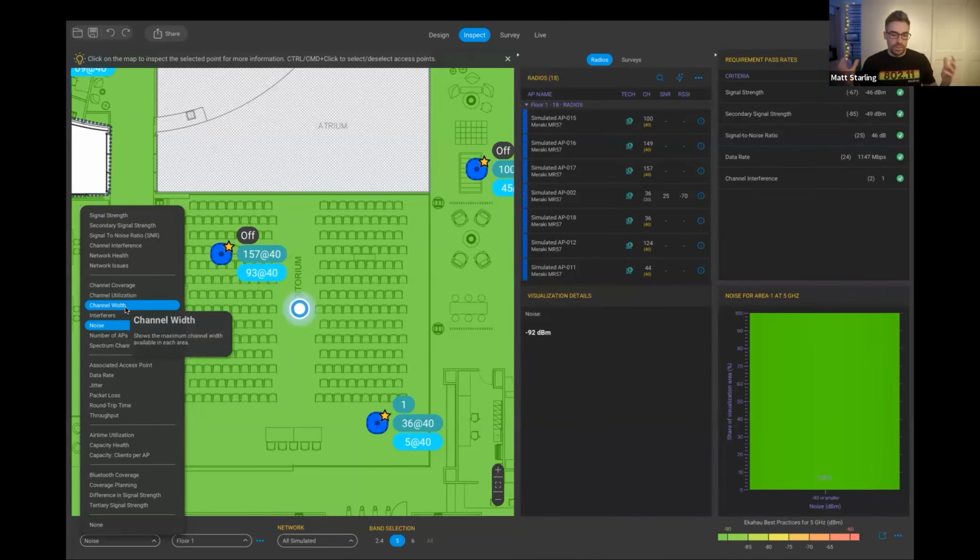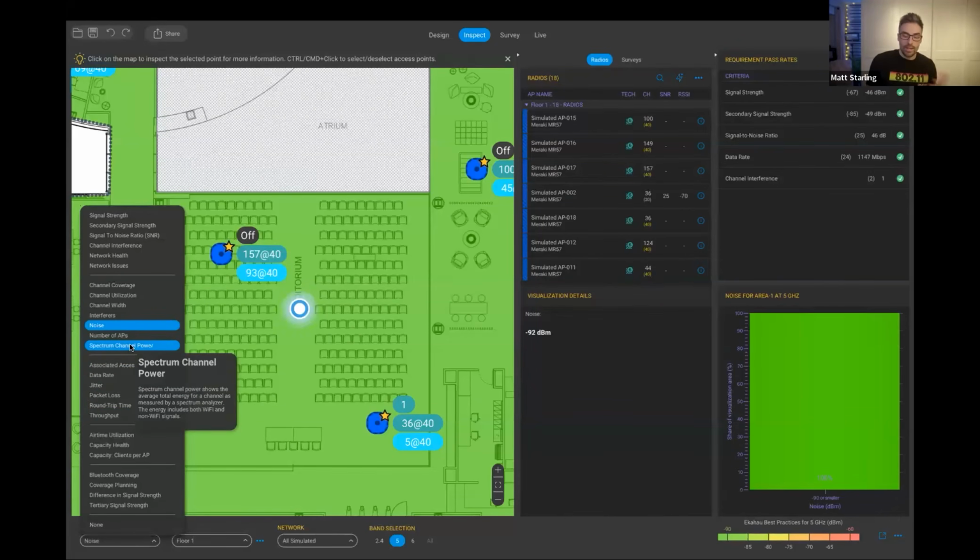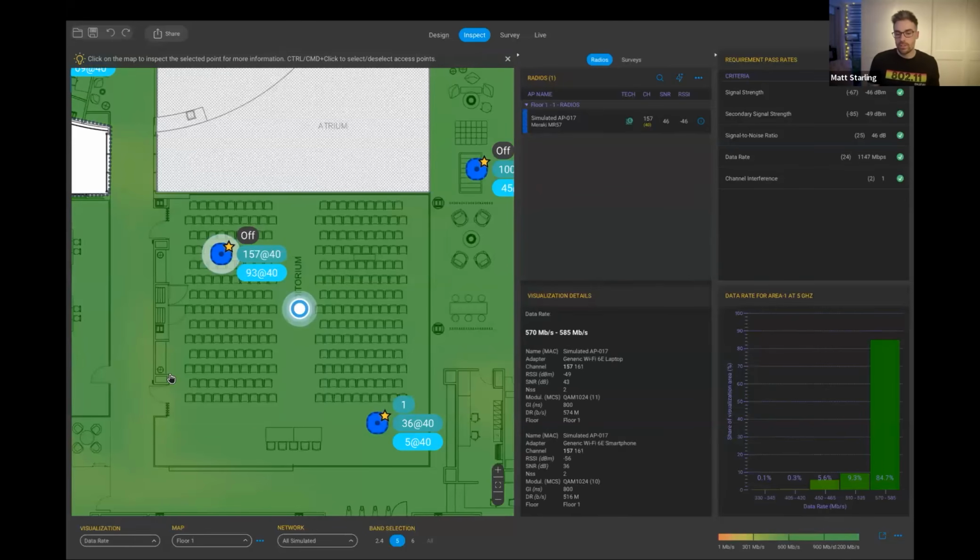If you leave it on the defaults of really wide channels, or you're trying to use even a 40 megahertz wide channel, sometimes your client devices will be paying the price of a poorer SNR value. That means they have less chance of using a more complex modulation and will send their data slower over the air, which means the overall speed of the Wi-Fi network is going to be slowed down.